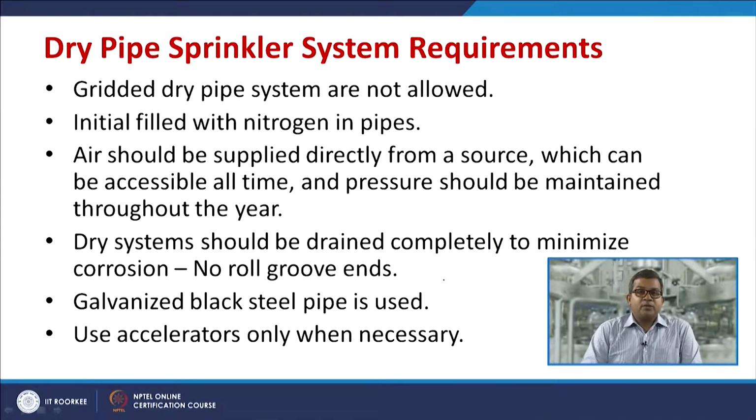There are dry pipe sprinkler system requirements, specific requirements that are attributed to the dry pipe sprinkler system. Gridded dry pipe systems are usually not allowed. The pipes are initially filled with nitrogen.